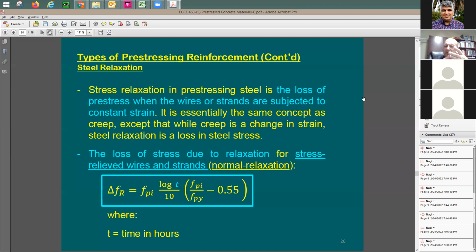It's going to be all about what? The concrete as a material. We have also mechanical losses. We have slippage in the anchorage at the beginning, at two ends of the concrete structure. So you are going to have a little bit of mechanical losses. We call this mechanical losses. And what else? The elongation of the rebar itself. The rebar is going to be losing the strain that you put in there. It's going to be relaxing a little bit.